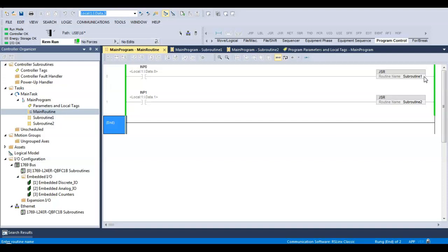So that's always available to you in a big program. Even in a 50-line program, you'd probably split that up too. You can just add a line with a jump and jump it back up here, and it'll keep scanning that until you take it out. You could put some inputs in there, so you could flip it off and on and let it continue on.